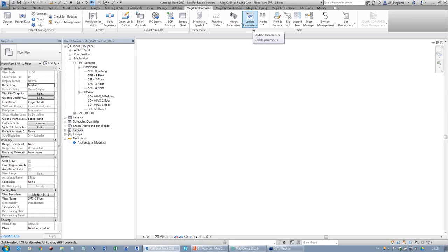But then when you want to filter out something, the only parameter that you can get to is the one called invert elevation. And that's an absolute height from the inside of the bottom of the pipe. So it's kind of hard to use for filtering stuff.